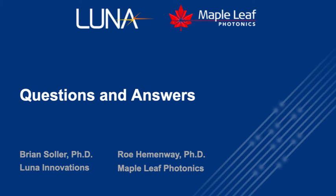Typically you start with a light source and sequentially illuminate the path that you want to characterize by monitoring photodiodes and looking at outputs. As you think about your layout and how you're going to design these complex circuits, it's very important to consider how you're going to configure this before you test it, because it often doesn't make sense to test a circuit that hasn't been configured.